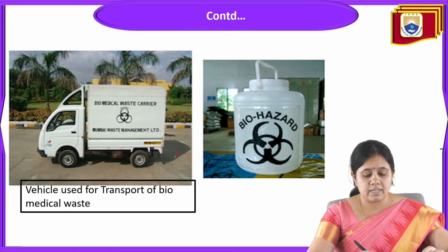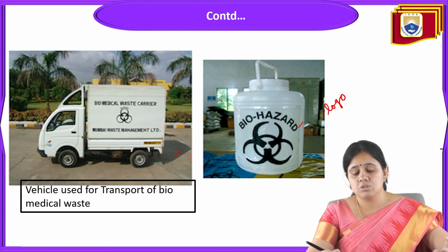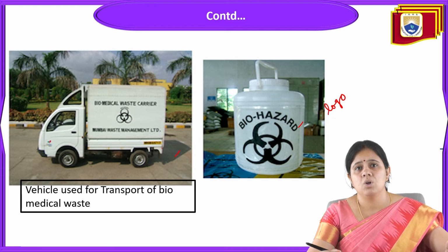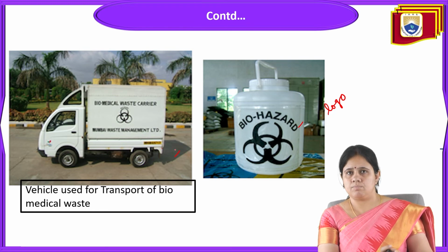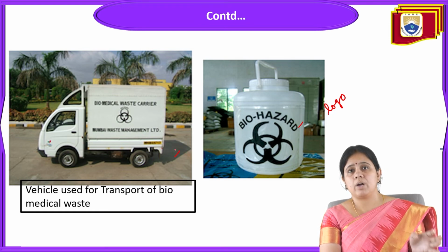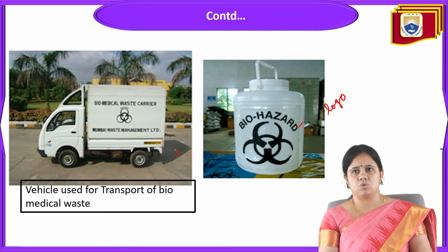You can see the pictures, and this type of logo should be used for biohazard, biomedical waste. This is the picture of the vehicle that should be used for transport of biomedical waste. See that the vehicle is totally closed. This is a very important thing to consider while taking the biomedical waste to its final delivery location, and while selecting the vehicles. The vehicle should be closed, so that it will not create any type of nuisance or unsanitary condition.